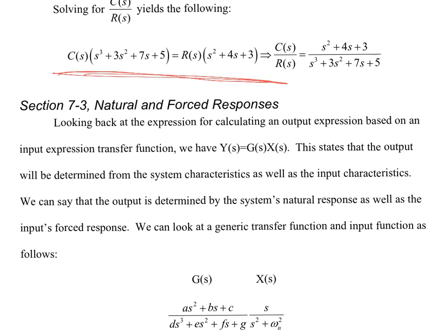I have seen, and I've never actually had the opportunity, but there are companies that actually can give you models of systems. What they do is they'll go to a plant and they'll do something that's called a bump test, which means let's get the system to be stable. Let's say the process set point is, let's say, 30%. You want 30% of the process to be doing something. And then a bump test is you say, I want to go 30% instantaneously to a new value. Let's say 40%. So you bump it, instantaneous change.